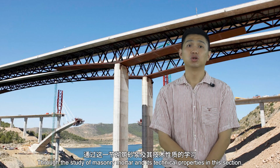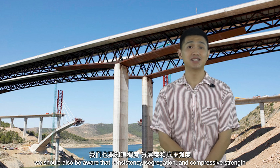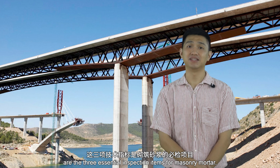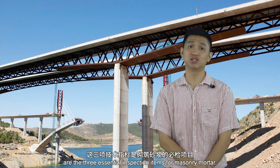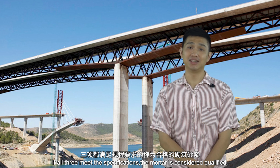Through the study of masonry mortar and its technical properties in this section, we should also be aware that consistency, segregation, and compressive strength are the 3 essential inspection items for masonry mortar. If all 3 meet the specifications, the mortar is considered qualified.